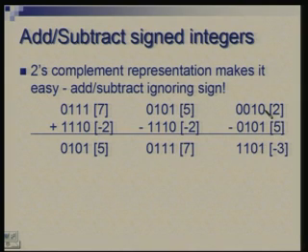In this case, let us do it step by step. So, you subtract 0 1 0 1 from 0 0 1 0. Here you get a 1, there is a borrow that eats away this 1. So, you get a 0, here again there is a borrow, you get a 1, there is again a borrow, you get a 1 here. Okay. Now there is ultimately a borrow from the left side, which like the carry we are neglecting.